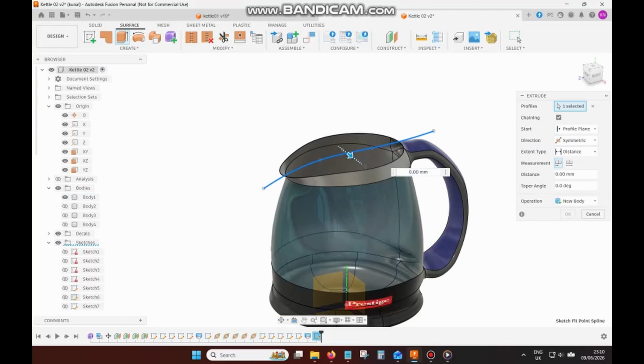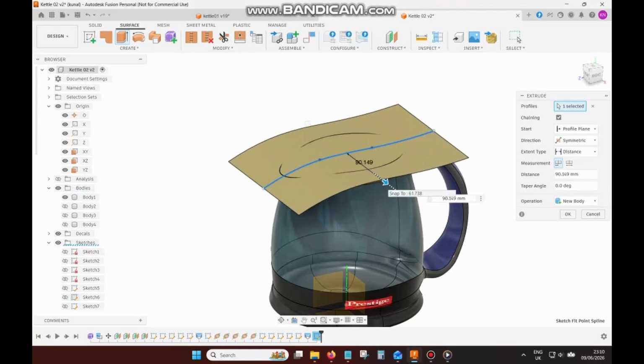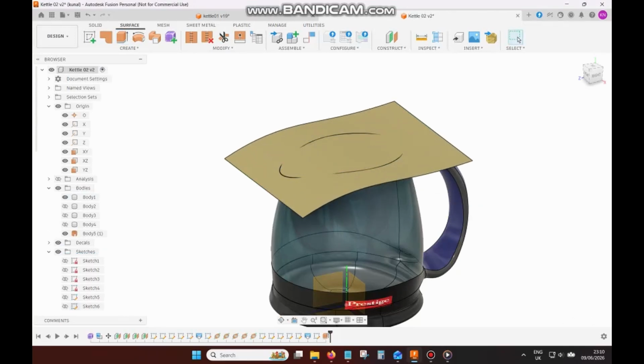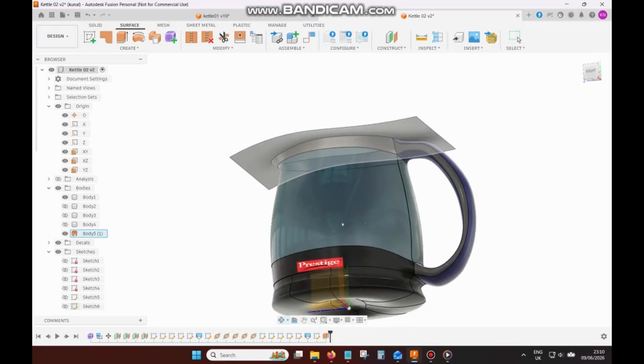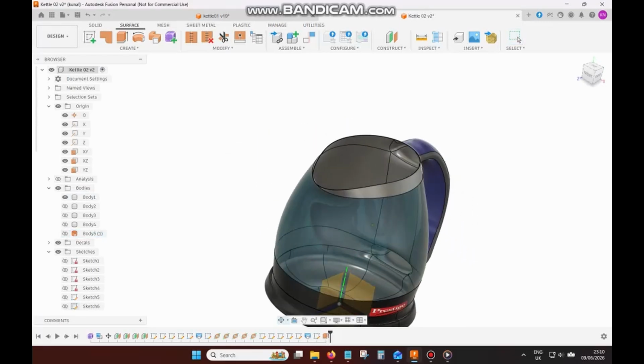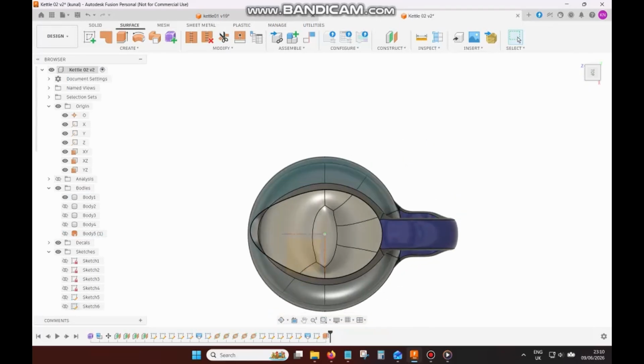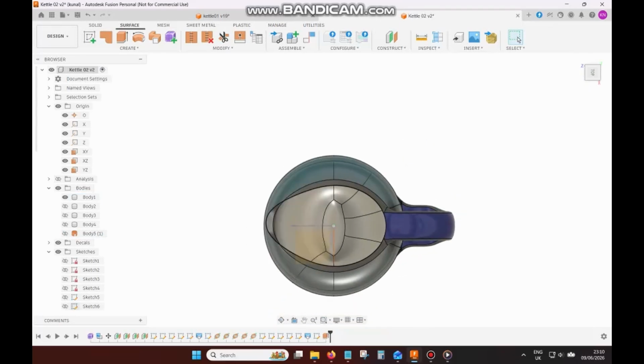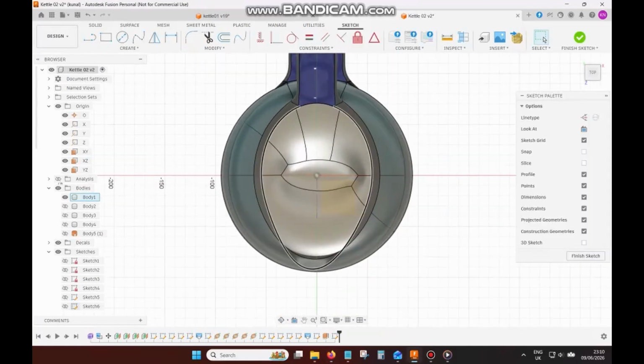So that covers that spout top. So that's that. And then I'm going to create a sketch looking straight down. It doesn't have to be on any particular plane, but I use the base plane. And I'm going to try and recreate that spout shape. As you can see, it's not actually symmetrical in the reference model, but mine can be. So I go ahead and do that.